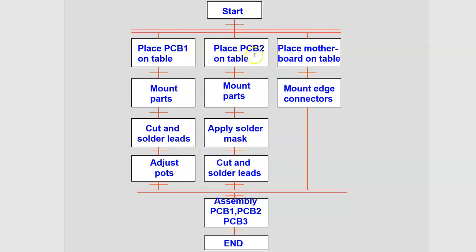Once everything is done here and all three branches are true, then we ask if we can transition out of this whole structure. Notice for each individual branch, you have to transition out of the last step. If it's not okay to transition out, it'll wait in here, or just keep looping, until this is done.